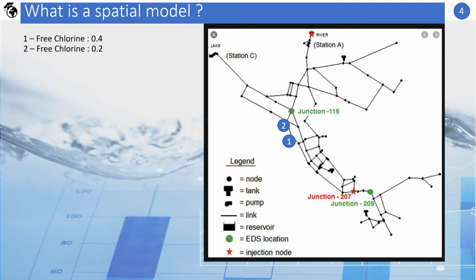How can the spatial model help in this case? Suppose that at a certain station, a measurement of chlorine concentration is obtained which is significantly higher than the station that precedes it upstream. There was probably no chlorine addition to the line. What is more likely is that the station is not calibrated. Furthermore, if the next station shows a lower measurement than both stations, it is clear that the middle station is not calibrated. The spatial model consists of two types of objects: